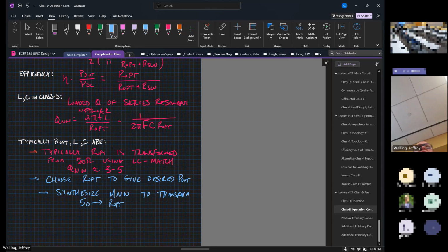That matching network in and of itself is already a bandpass network, so we don't need to add a definitive series resonant network. LC matching networks are inherently bandpass. We said that they might have a skewed shape, but hopefully you'll recall from the homeworks that when we plotted the frequency response, there was always a bandpass shape that might be favoring one side versus the other.